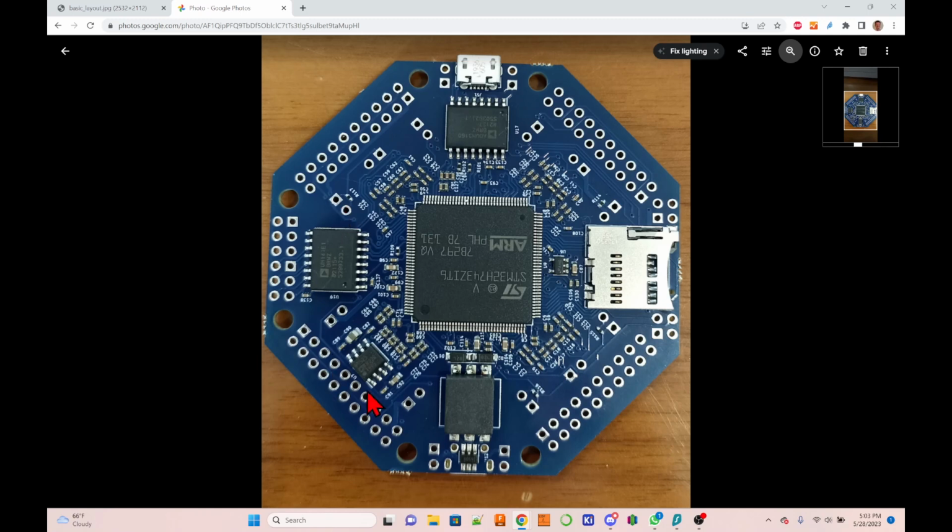And of those, you need in total, what, 11? Yeah, you need 11 of those. Or I would recommend soldering all 11 of them. But before you do that, there are 4 0 ohm resistors that need to be removed from the board. And just so everyone knows what a 0 ohm resistor means, in order to operate this board by itself, there need to be 4 0 ohm resistors, and I'll show you the position.